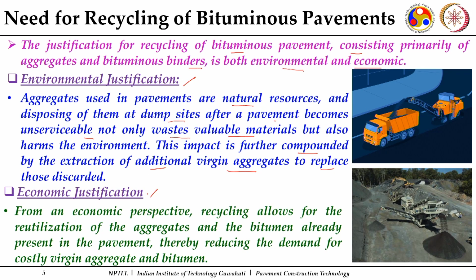Economic justification: recycling allows the reutilization of the aggregates. Aggregates are costly components. There is also binder, which is again a very costly component. Because we are making use of both aggregate and binder, it can be very well justified in terms of economic operation. It thereby reduces the demand for costly virgin aggregates and bitumen.